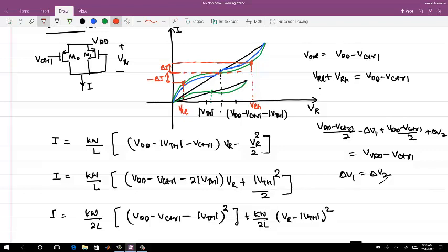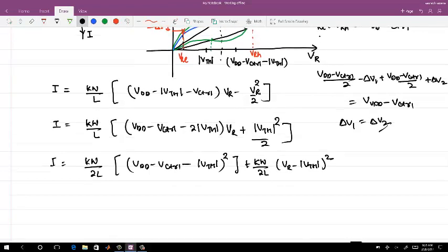This is going to change the resistance, but the change in the resistance on the two sides is the same. The derivatives, di by dv, will be the same. Because of that, you will not see the noise coming from the supply to the output nodes. Anything on this so far?